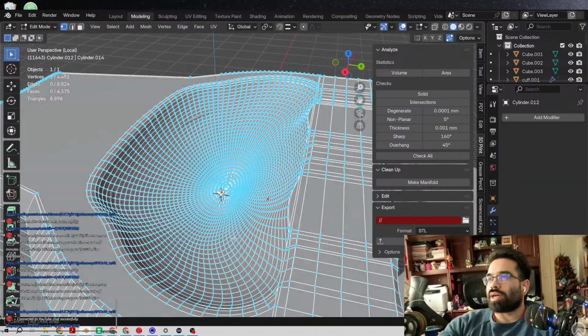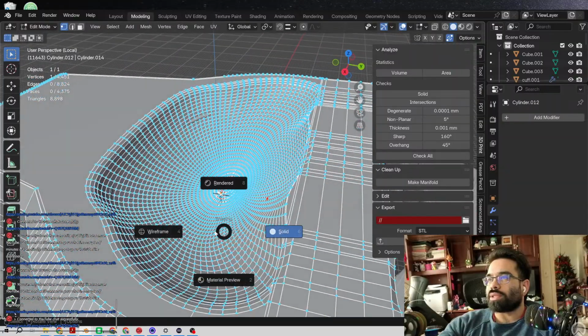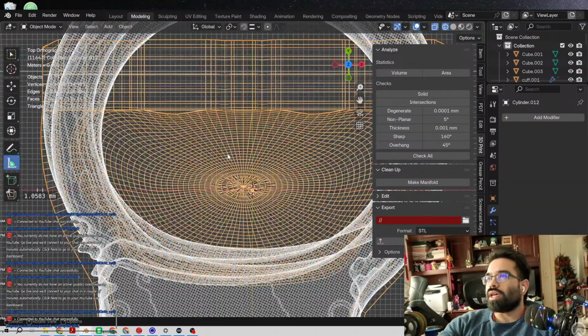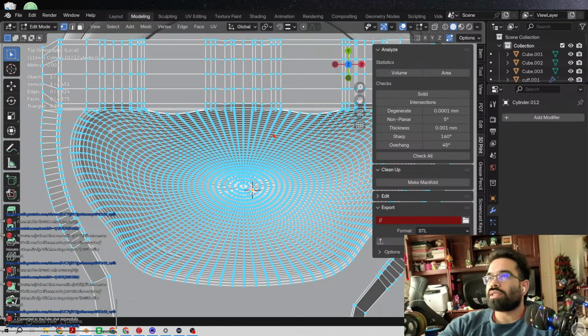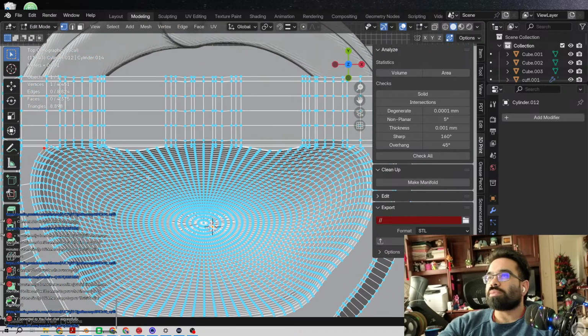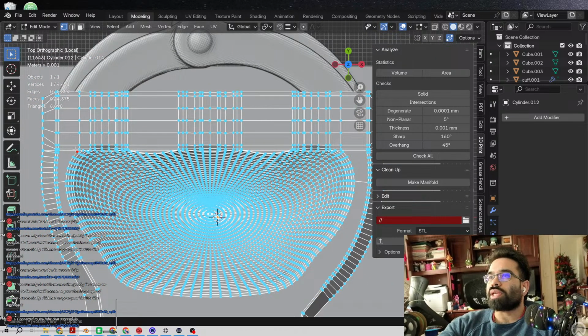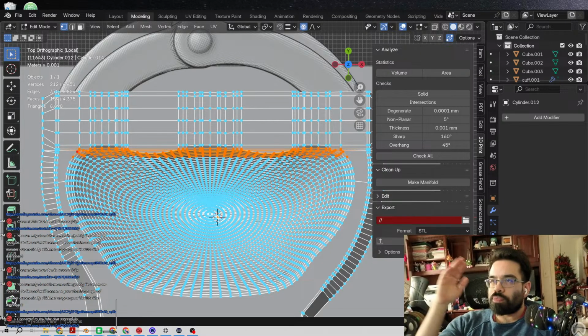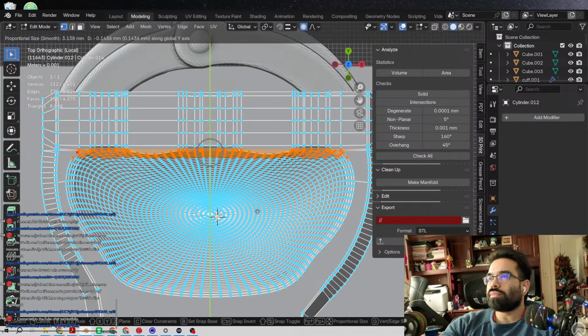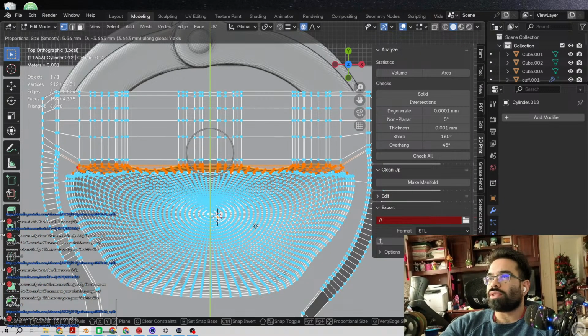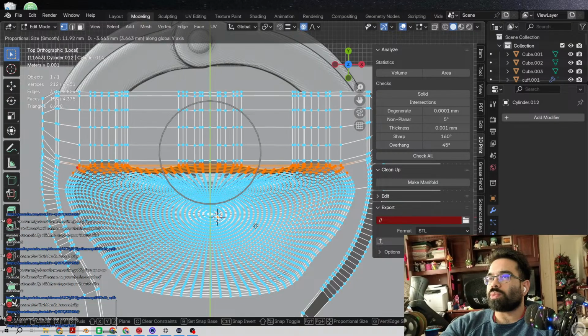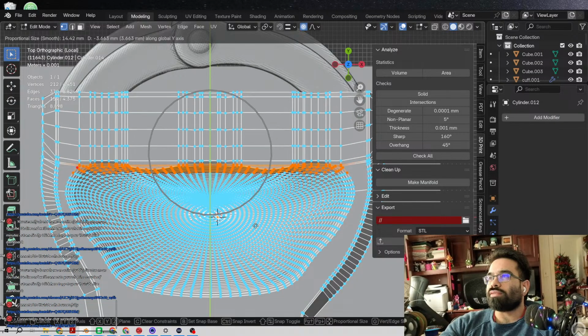That's something that you'll be doing a lot in Blender. And by that I mean just taking some of these vertices and maybe using proportional editing. It's a really awesome tool. Say you want to grab these, you'll click on proportional editing, and we just want to bring it down. So we're gonna hit G for down, and then wheel scroll to widen your range of effect here.